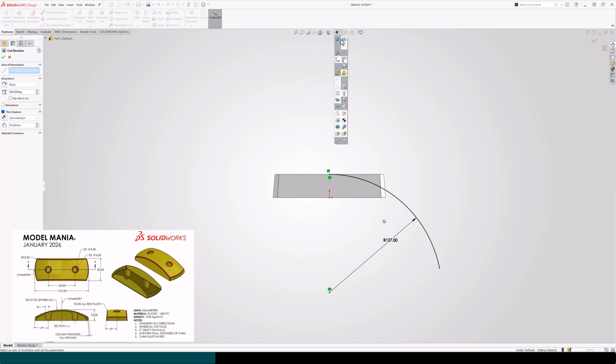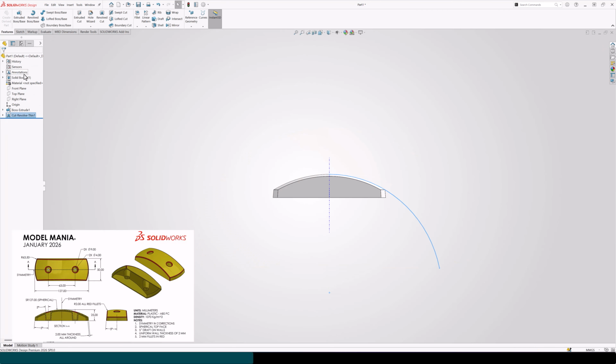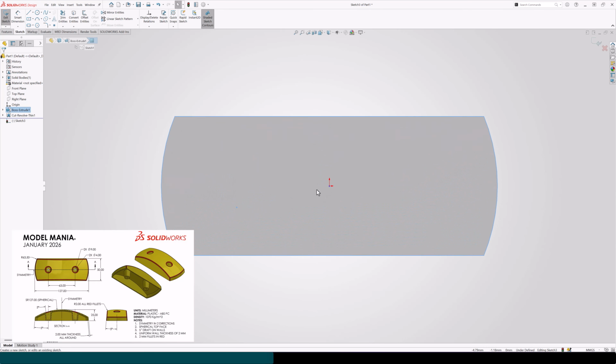But what I'm going to do is revolve it around this axis, and I'm going to make sure that I don't use dummy geometry and I just do a thin feature and basically use that to connect my contour revolved around that axis so that I can save time. I need to click to place my holes here.